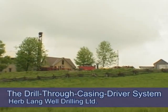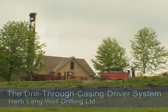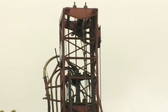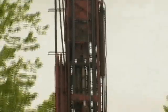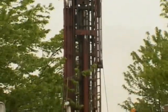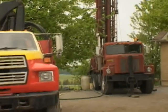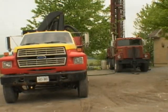The drill-through casing driver system is well suited for drilling in unconsolidated material, offering excellent penetration rates, especially in conditions that present lost circulation problems, such as cobbles and gravel. This system advances the casing at such a rate that the time required to weld casing sections may exceed the time to install these sections. The system utilizes conventional circulation with air flushing media.